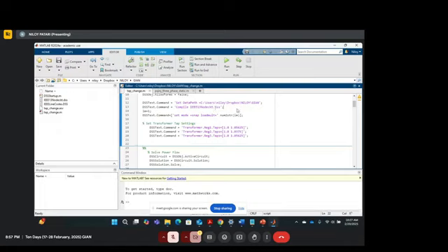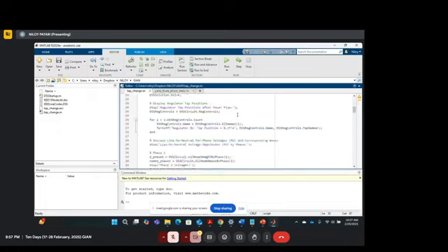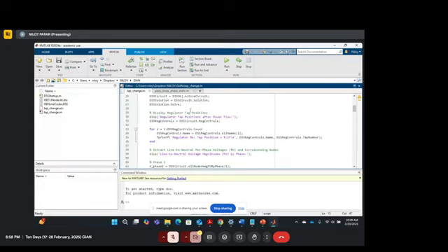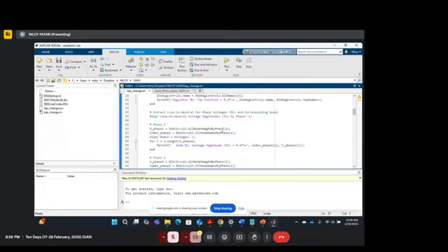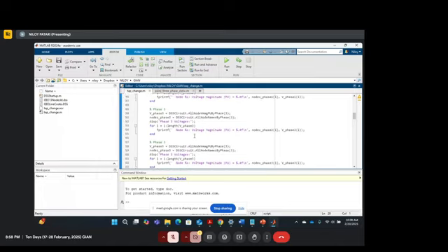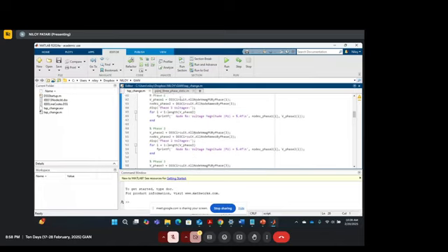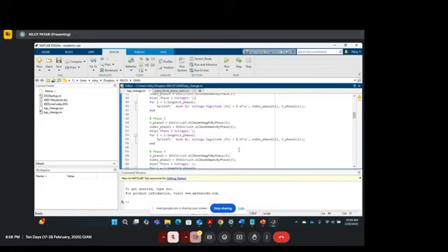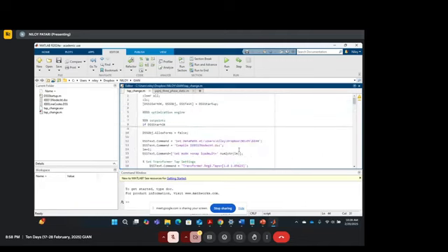And then after it does that, it solves power flow, DSS solution.solve. Then I'm displaying the same regulator tap settings, and I'm also looking into the voltage of phase A. Because you have a multi-phase distribution system, it takes phase 1, phase 2, and phase 3, so phase A, phase B, and phase C. So let's just run this.